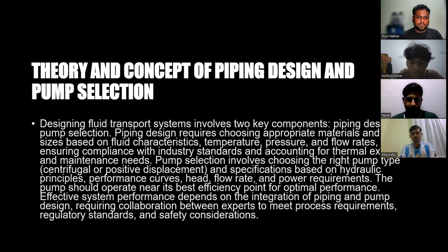Pump selection involves choosing the right pump and specification based on hydraulic principles, performance curve, head, flow rate, and power requirements. The pump should operate near its best efficiency point for optimal performance. And also, efficient system performance depends on the integration of piping and pump design, requiring collaboration between experts to meet process requirements, regulatory standards, and safety considerations. And the next one will be presented by the next member.